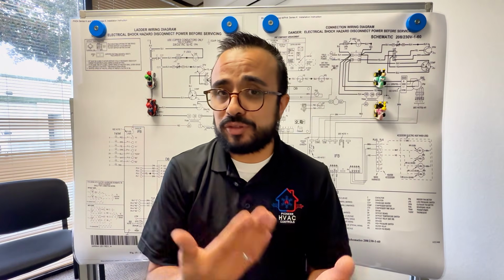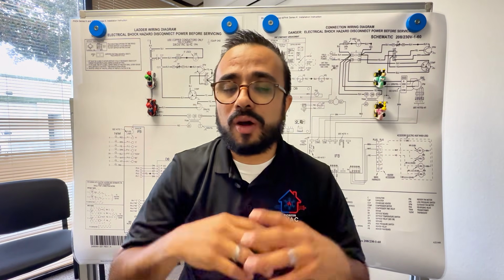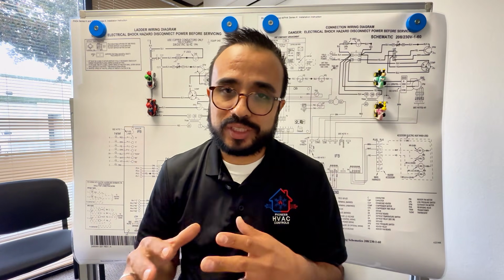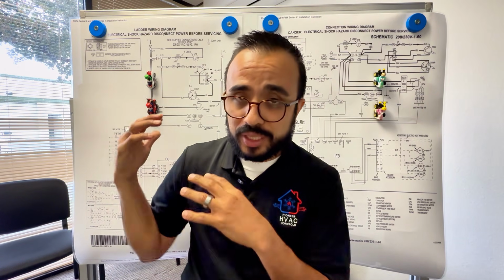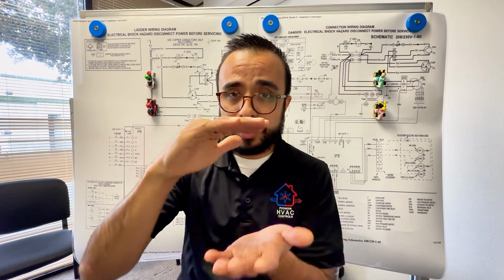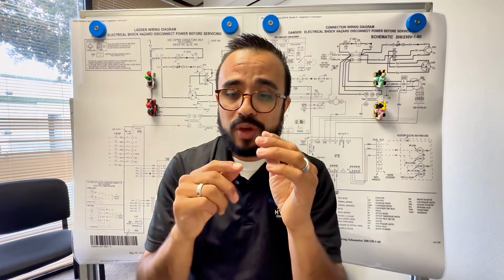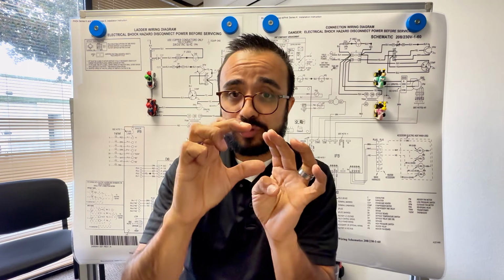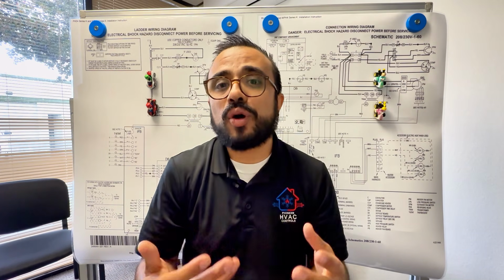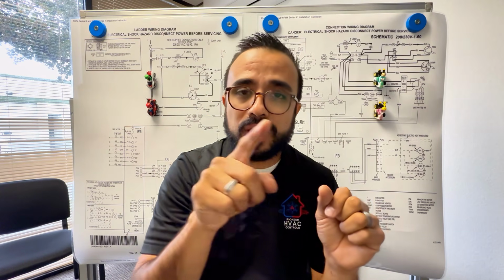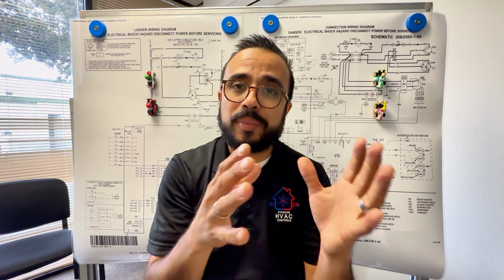You see how pressure switches and your thermostat all tie in with the low voltage. With the ladder wiring diagram, you're able to see how on the bottom you have your low voltage, on the top you have your high voltage, and what differentiates both is your transformer in the middle. And your pictorial connection diagram is a lot easier because you can literally follow the lines as to where the power travels.